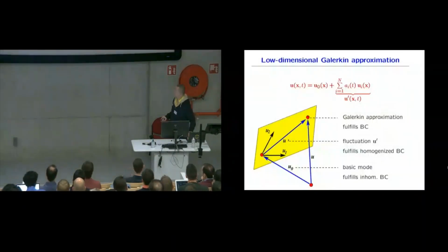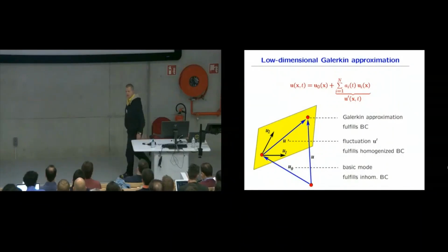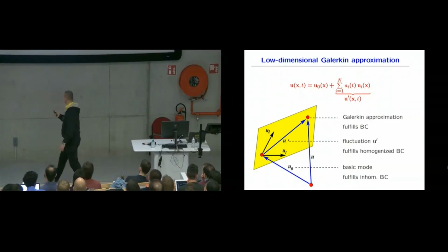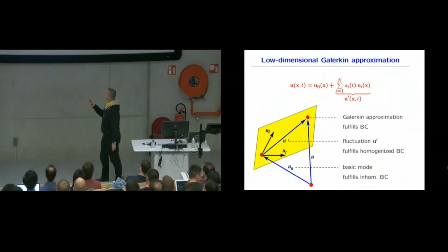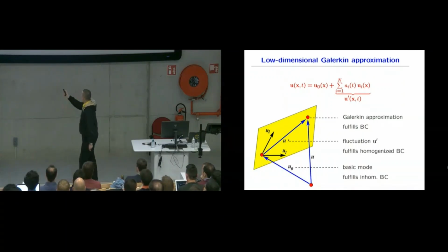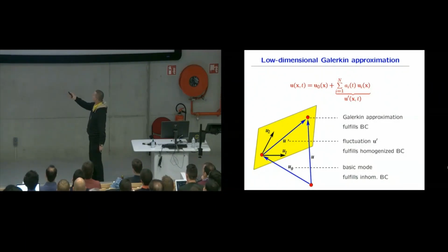We go now to the periodic cylinder wake, and we start a bit more first-principle based. So now we want to have something like a low-dimensional representation of the cylinder wake. We could take, for instance, the steady solution here and some stability modes here, and then we have time-dependent coefficients. In this case, this marks the fluctuation, and this is kind of the basis. So in this case, we live on something like an n-dimensional space.